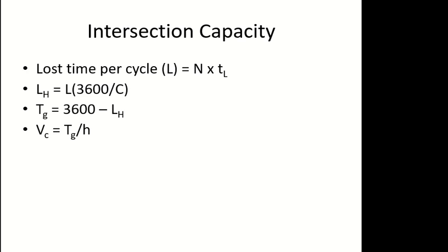And then if you want the capacity, again this is from method 1 of last example. During effective green, the gap between the vehicles is equal to saturation headway, which is H. So total time available divided by gap between the vehicles will give you number of vehicles, VC, which we call as the capacity. This is exactly step by step what we have done in the last example in method 1. So now if you look at the equation of VC, it has TG in it.